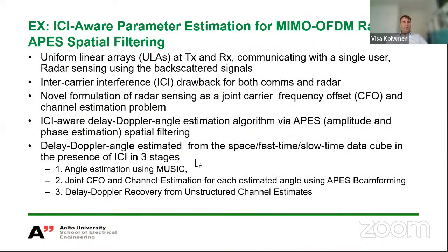I'm afraid I'm probably running out of time, so we have one additional design here that is basically using uniform linear arrays and performing parameter estimation of MIMO OFDM radar, and that allows you to estimate the delay, Doppler and angles for different targets in three stages.